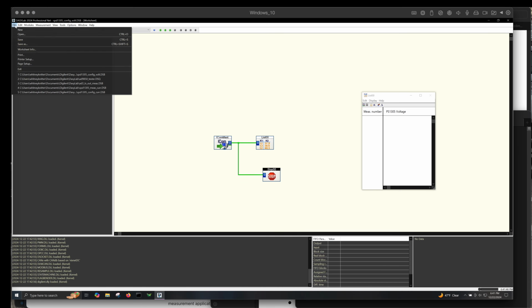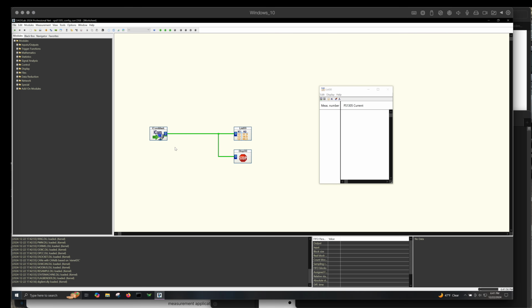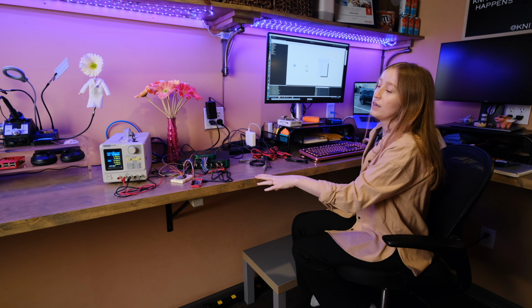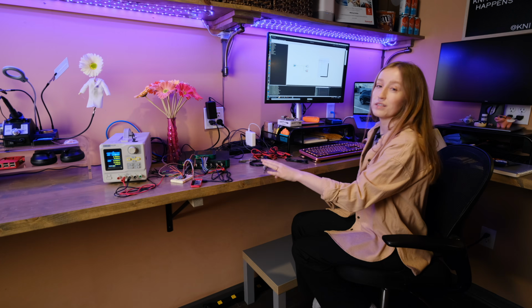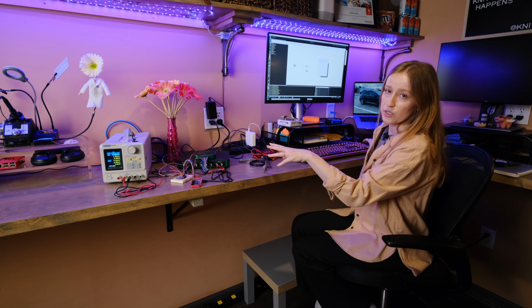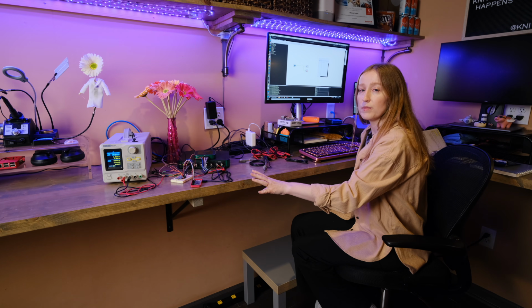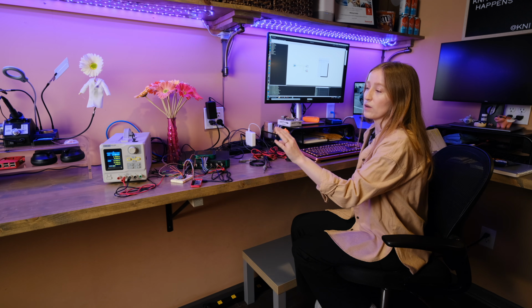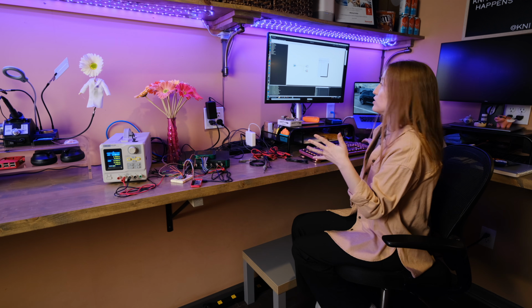The second test is the same thing, but to configure the current. So for a Raspberry Pi Zero, the maximum it should ever draw should be no more than 2 amps ever. So I'm going to set my power supply to 2 amps. That doesn't mean I'm driving 2 amps into my Raspberry Pi Zero. That just means the power supply will let the load, the Raspberry Pi Zero, draw up to 2 amps before it limits it at 2 amps.